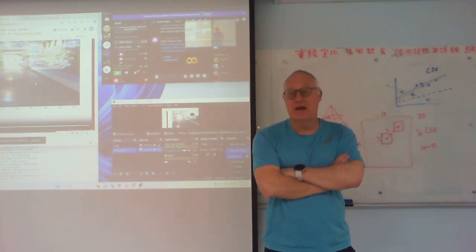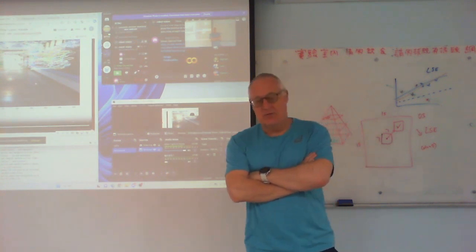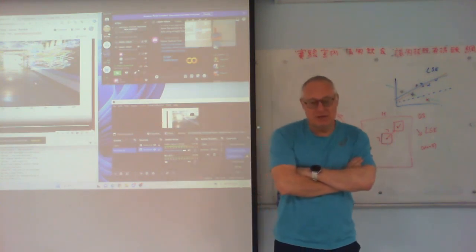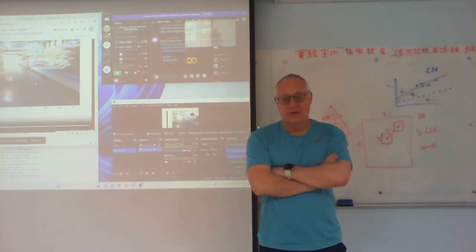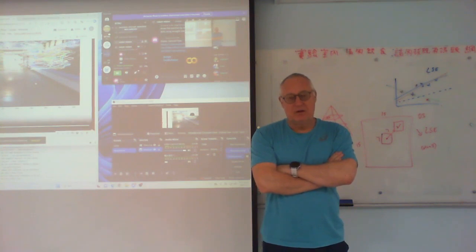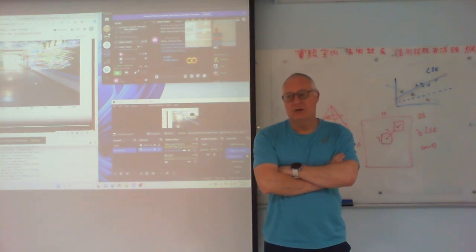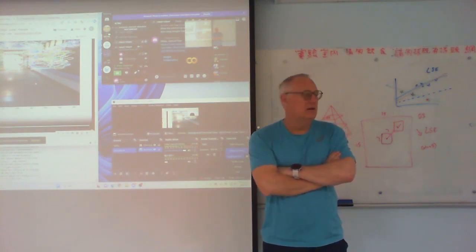Yes. And also SLAM is now completely changing away from 4x4 transformation matrices to use PGA. And for SLAM, it makes a lot of sense, right? Because you are then guaranteed to get a motion that the robot could only do.